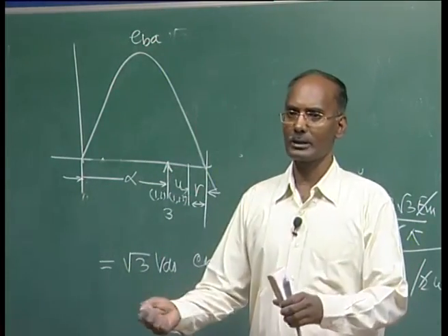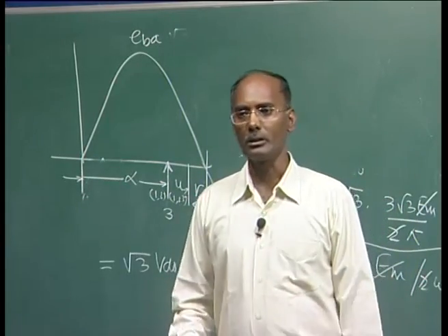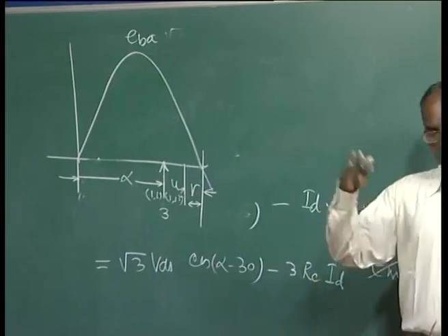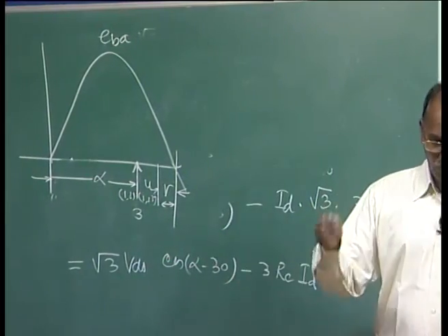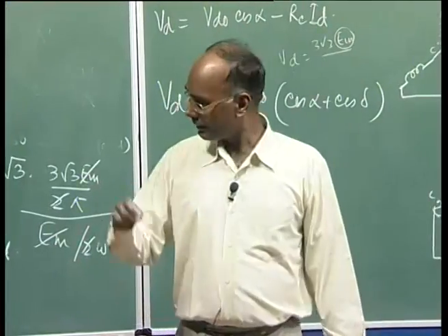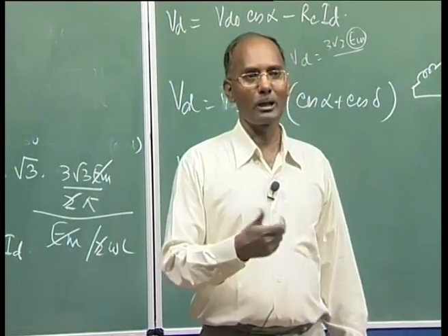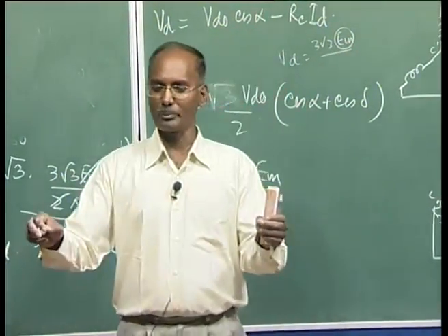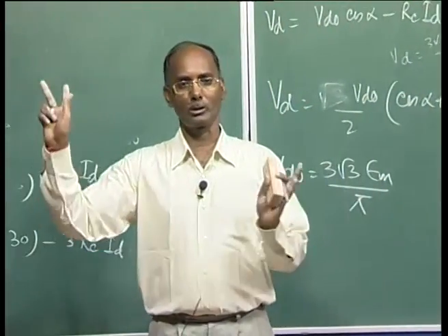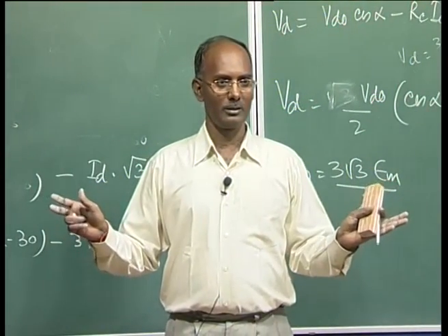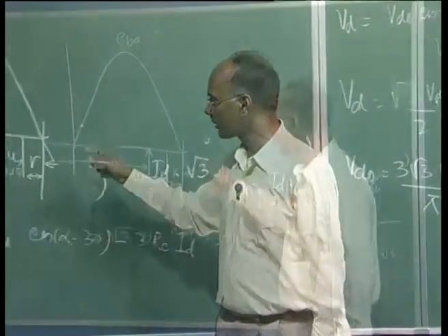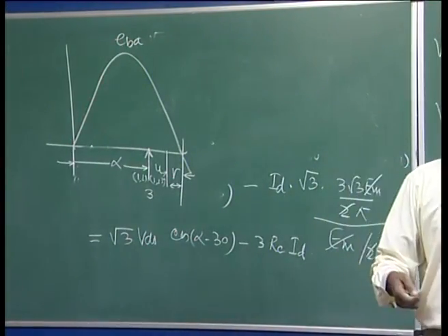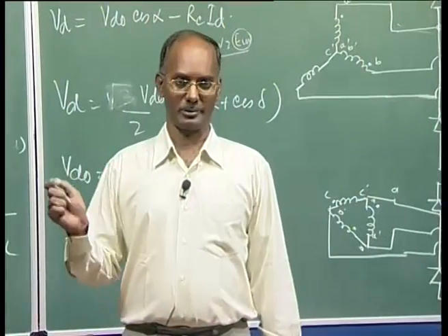But if there is a fault, a very severe condition, we still cannot tolerate it, and there may be commutation failure. We will analyze commutation failure later on, and we will see that it is self-curing, so there is no need to worry. If there is a commutation failure in one cycle, in the next cycle it will recover automatically, so the fault is cleared. But no doubt commutation failures are not allowed, because they inject more harmonics into the system, which is dangerous.